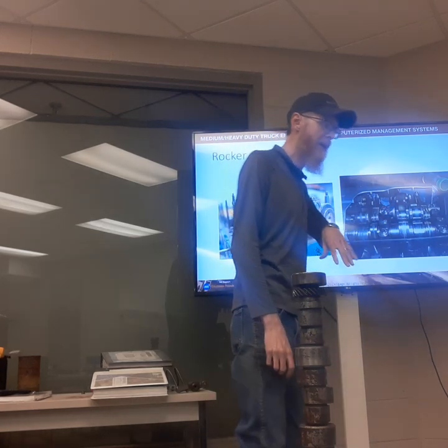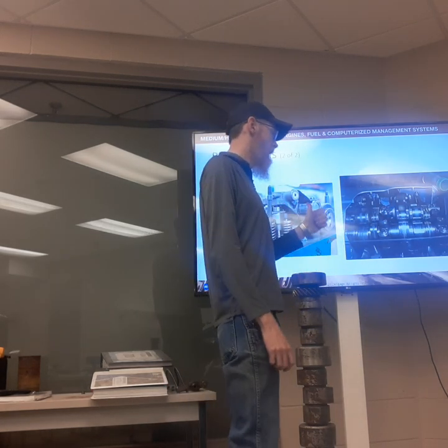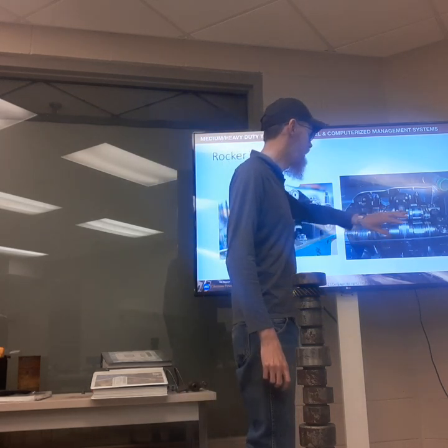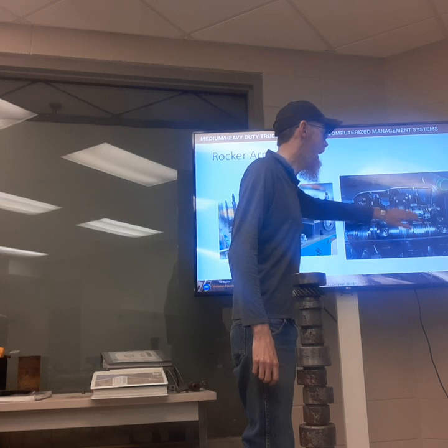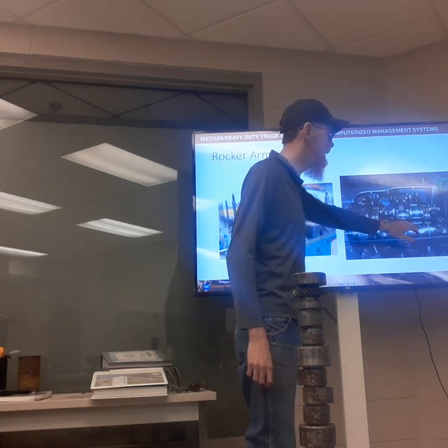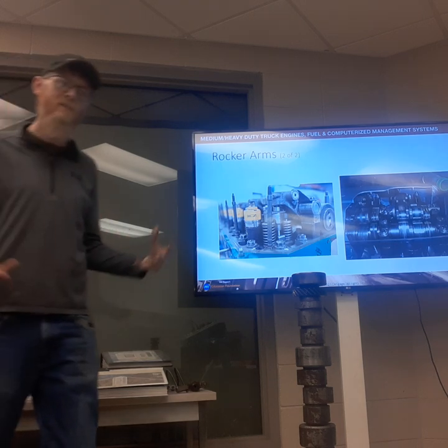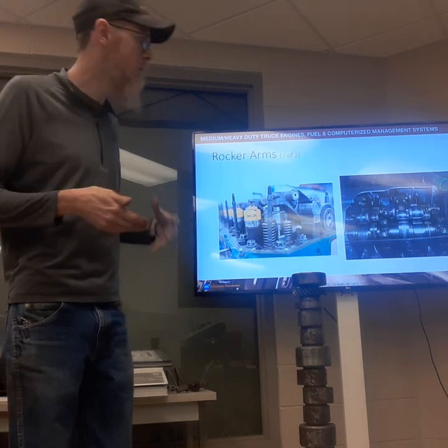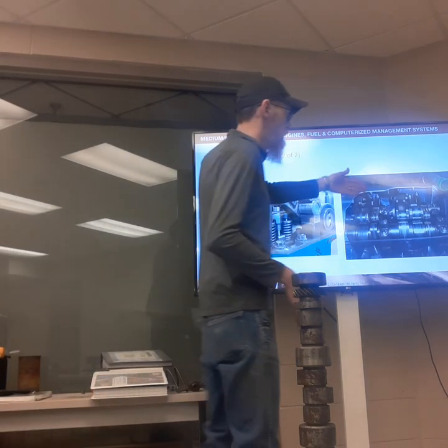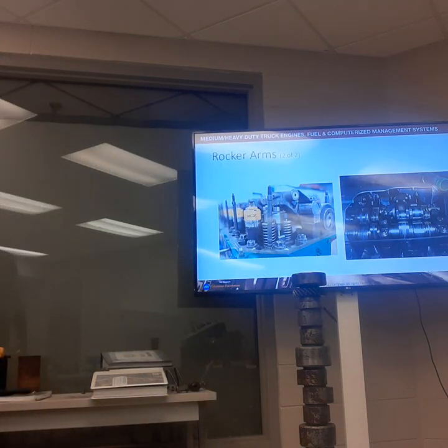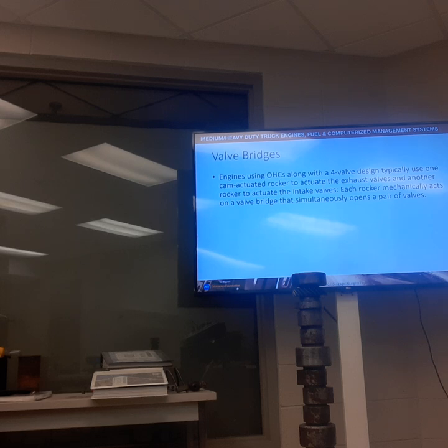So instead of any kind of cam follower, like we looked at in the pushrod engine, on this overhead camshaft design, the rocker arm itself has a roller that comes in contact with our camshaft lobe. So the roller also helps with the friction between those parts. We still have lube oil there, but the roller just reduces friction between the camshaft and the rocker arm.